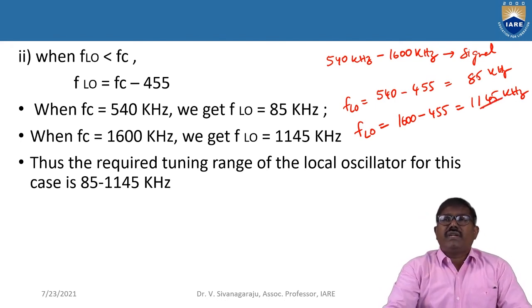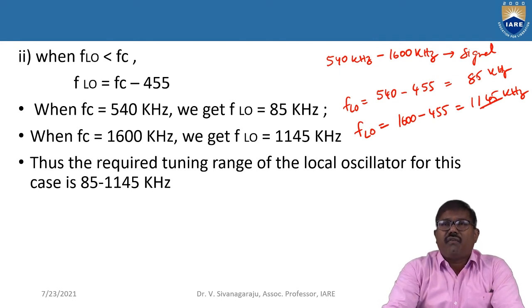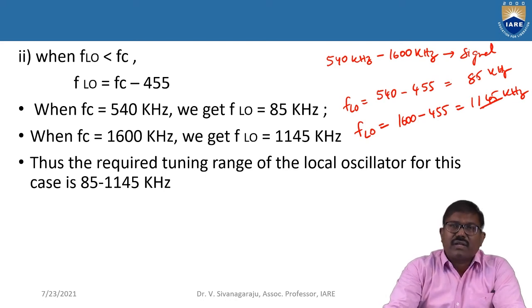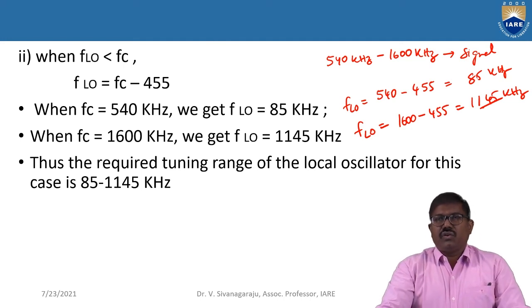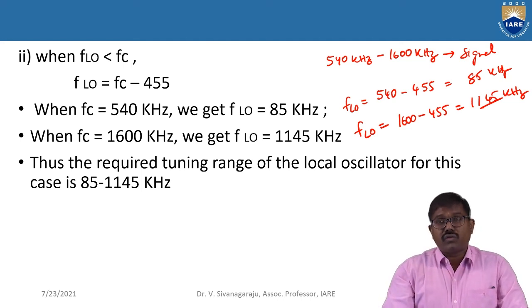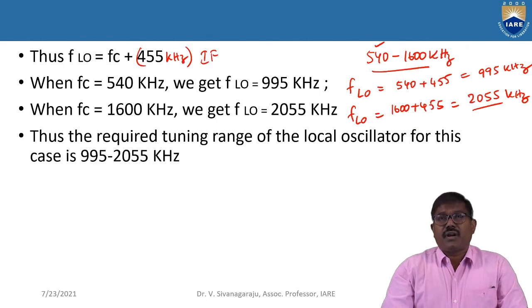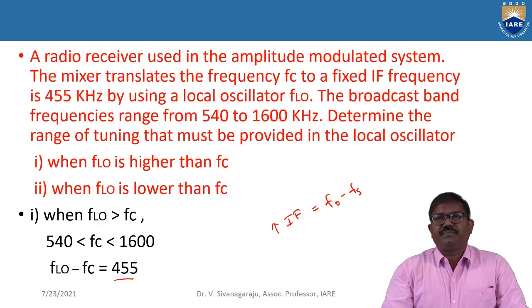So in the two cases, we found the local oscillator tuning range. Thus the required tuning range of the local oscillator for this case is 85 kilohertz to 1145 kilohertz. So these are the two cases by which we solved the given problem.